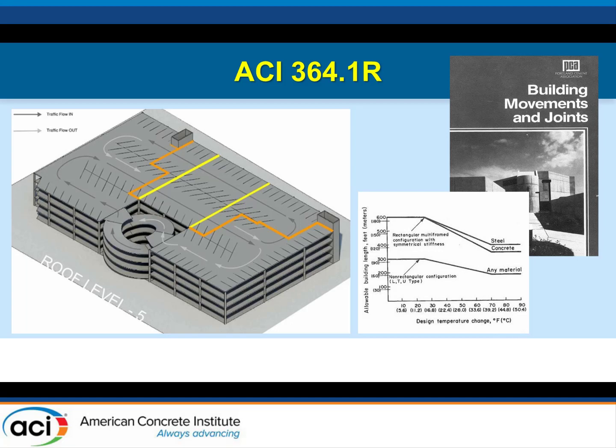I think what happened was they didn't necessarily get them in there effectively, because when we came back and looked at the garage another 10, 20 years after that, where the orange lines are, that's where the garage created its own expansion joints. It basically unzipped itself. So, this is one of those cases of the adage where the structure really was smarter than the engineer that designed it.